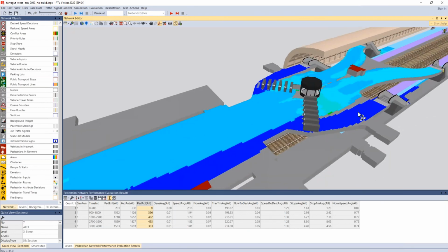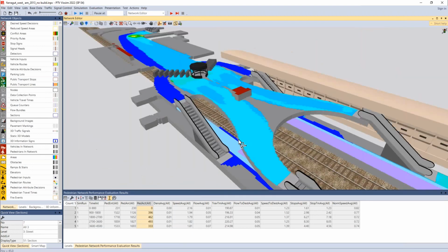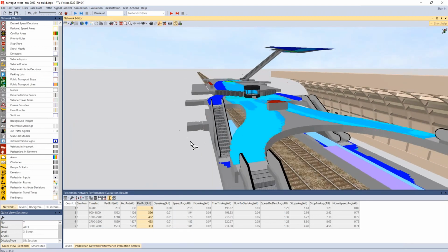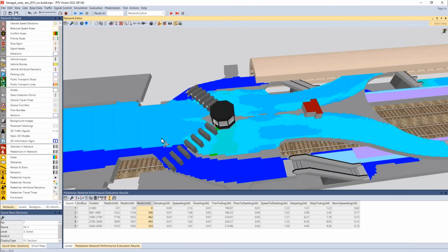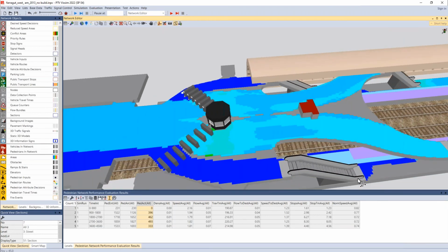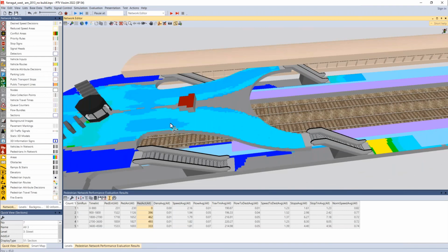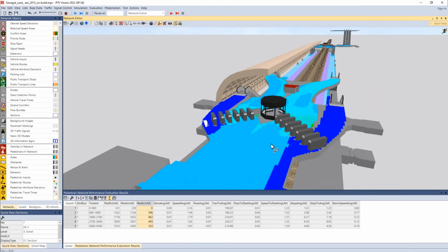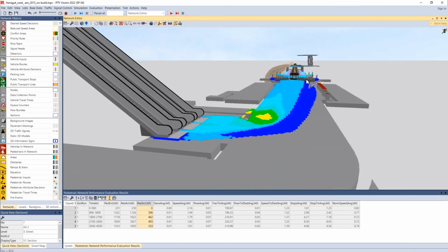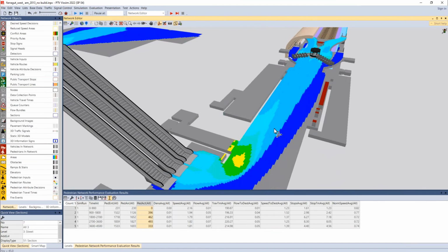That's why specifically on Farragut, we see that the mezzanine level is built in a very specific way, where you don't see any right angles on the pedestrian movements, right? So the pedestrians come in and they flow down like this, and then when they're leaving, they flow up like this, and those 2 flows are meant to avoid each other, right? And so this is how you can use Viswalk to plan out a pedestrian space to avoid situations like this, where you have a large flow that needs to take a right turn, and then another conflicting flow that also is taking a right turn, and it's kind of a blind corner, right?